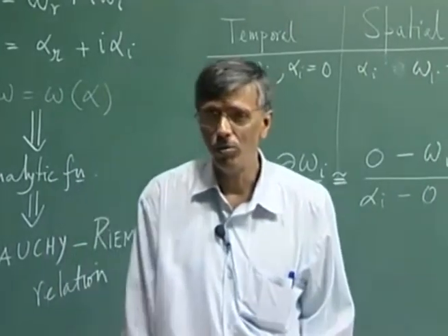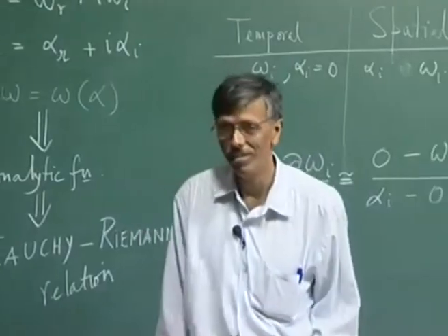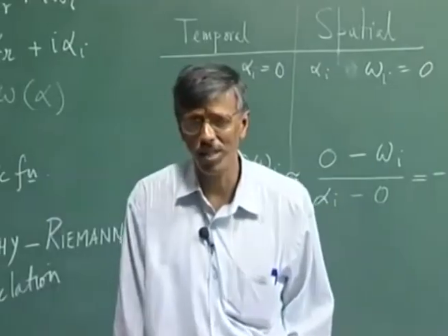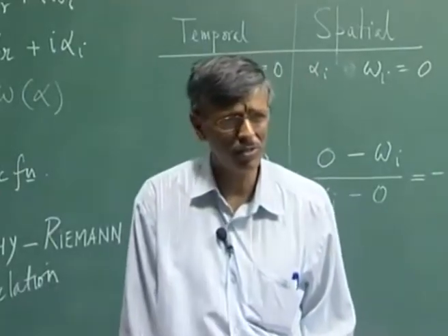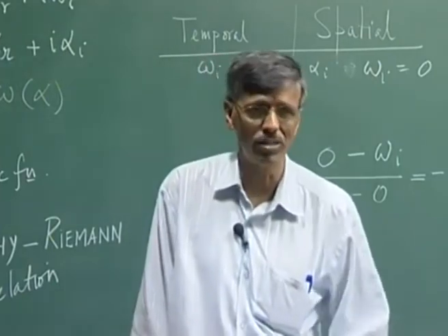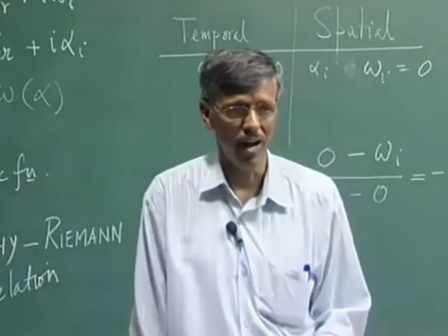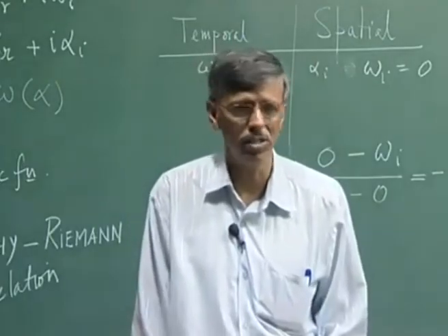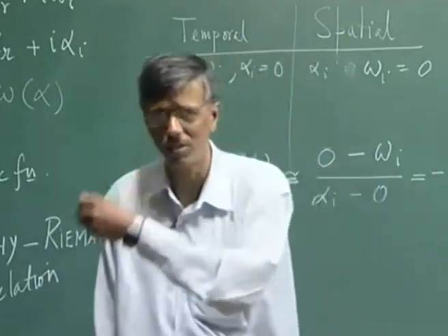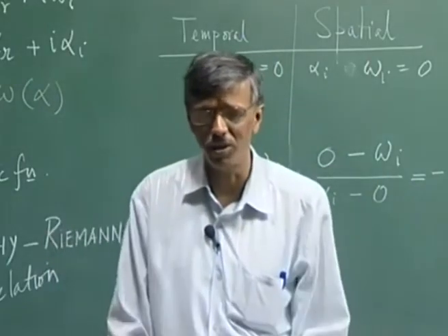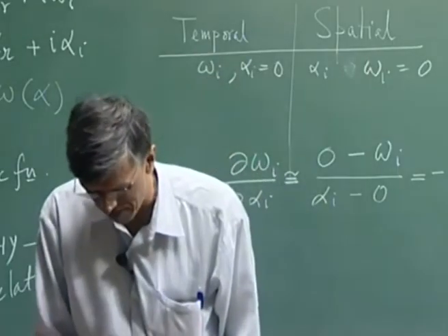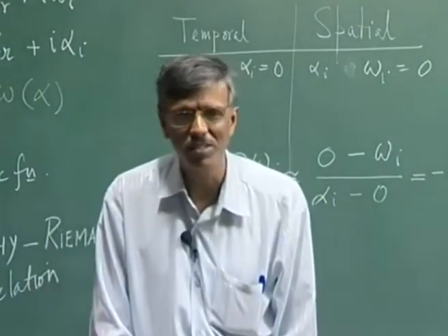Now, we can similarly also conceive of a situation where the shear layer is disturbed from outside. Why do we have to really think always the disturbances are created inside, and we need solutions which decay with y. I can have the completely other situation, that I do not create any disturbance inside the shear layer, but the disturbances are going up. In fact, one of the very clearest manifestations of this is in the weather system.